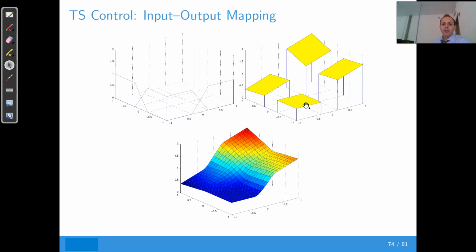So when you think of a fuzzy system as an input-output mapping, if you remember, the fuzzy relation corresponds to a, well, in this case, because your controller is controlling two inputs, the error and its derivative, the control input can be described by a control surface.